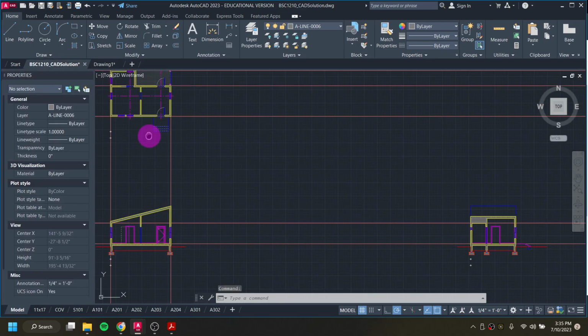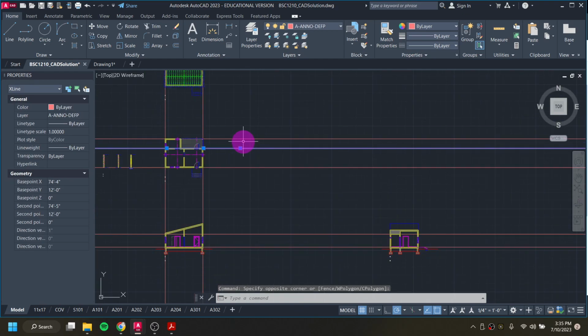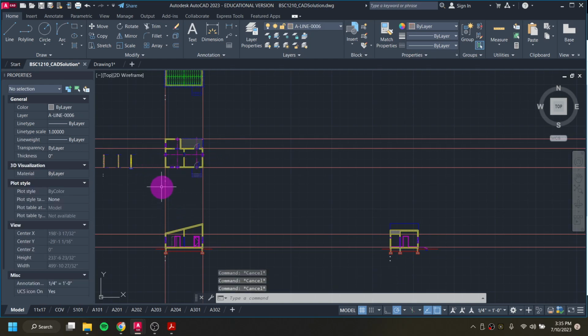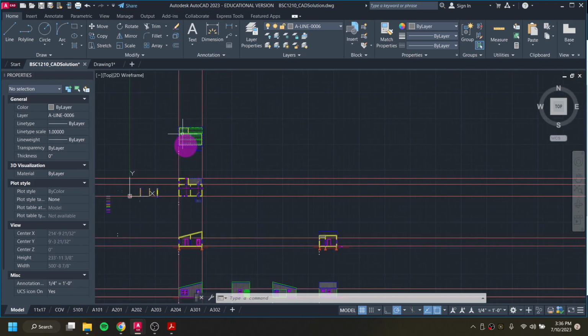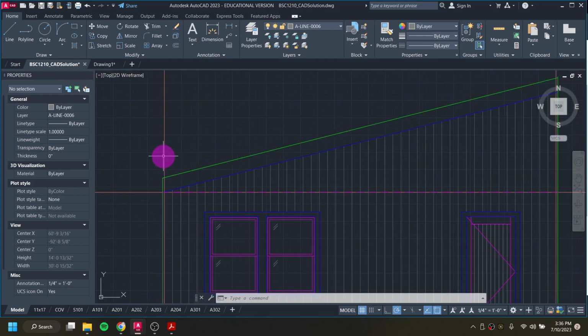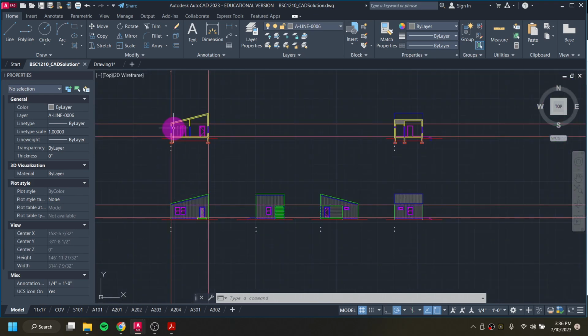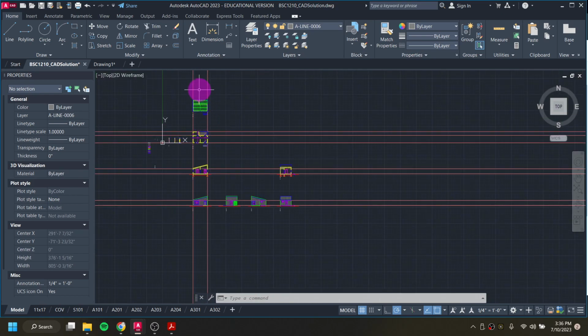One thing you'll see when I go into my finalized version of the drawings is I have a lot of these depth point lines. I have these construction lines or rays that are just going on for infinity. This isn't a requirement in any set of drawings, but what I like about it is it helps me line up where my views are going to be orthographically, which can be pretty helpful when I'm making my section view and stuff, because I don't necessarily have to recreate measurements. And I also just like having everything aligned this way.